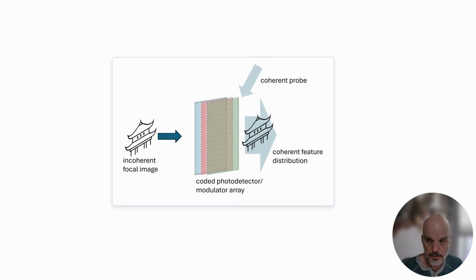This addresses the core bottleneck in modern imaging systems, that the basic function of a modern camera is to turn the massively parallel optical input into a serial electrical signal. That's not the way biological systems work. Of course, the visual cortex is highly parallel, with more than 1 million channels potentially fed into the cortex. And here we're imagining that we can build a similar parallel interface that has an incoherent detector array and creates this coherent wavefront that we can then process in our associative memory.